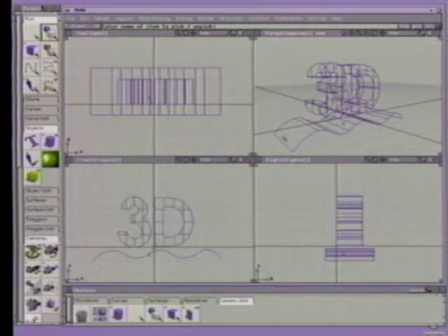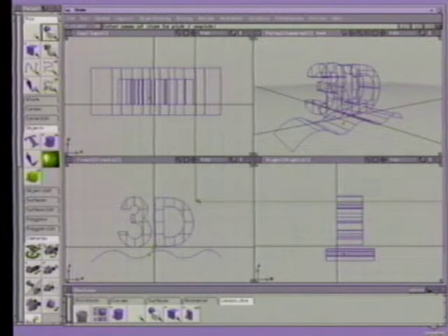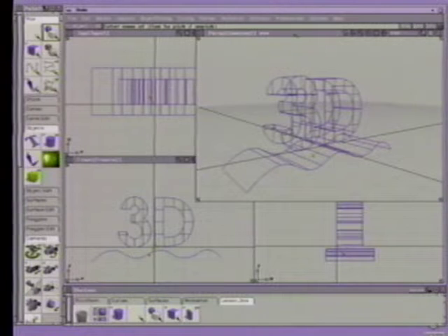Turn your attention to the perspective window that is located at the top right of the screen. Click-drag on the Resize button with the left mouse button at the bottom left of the window. Drag out to make the perspective window bigger on the screen. Sometimes you need a larger window to work with geometrical details.